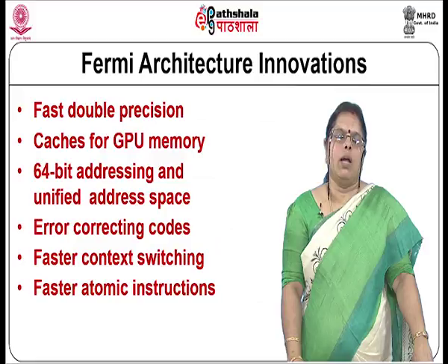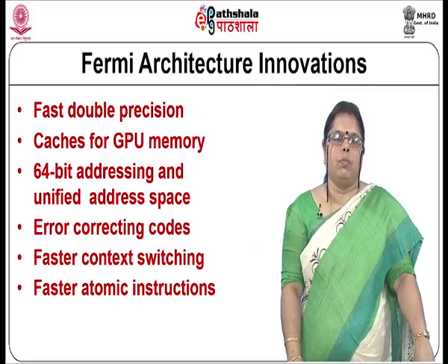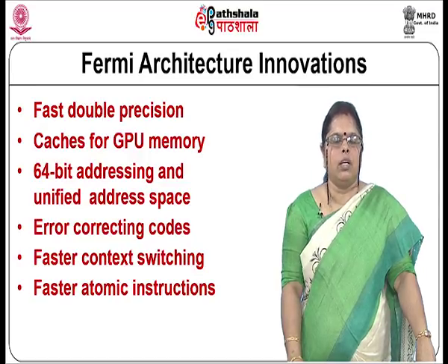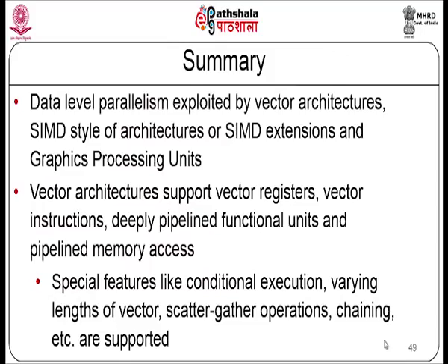You also have other innovations with respect to the Fermi architecture like fast double precision operation, caches for GPU memory, 64-bit addressing and unified address space, error correcting codes, faster context switching, faster atomic instructions.